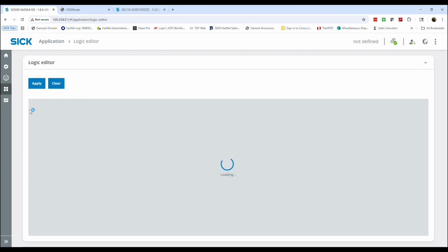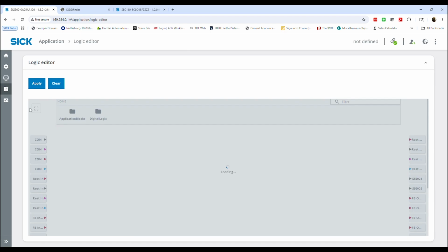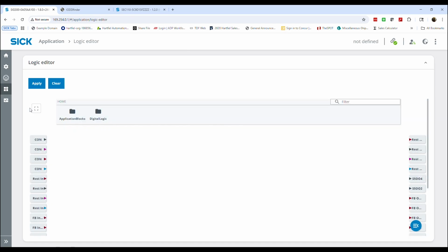This is where we're able to really bring some of the smarts. The SIG300 makes the IO-Link information really easy to see with that IODD viewer, but we're really able to take this and do a lot of things that a PLC may be able to do. Say we've got a tank level, say we've got an application like this where we just want to know that we put on, say, a label on a package. We want to do some simple counting and everything. You don't necessarily have to pull that into the PLC. We're able to do that right into here.